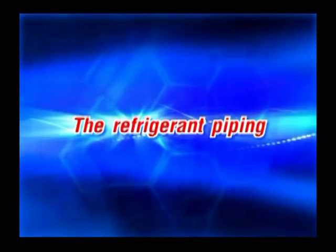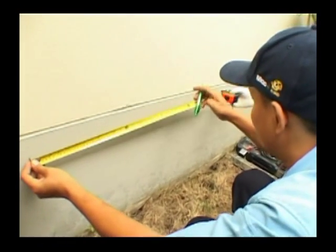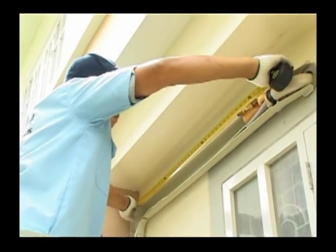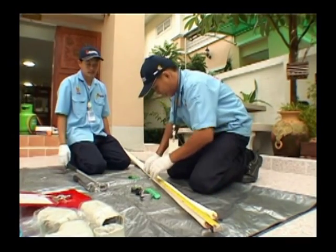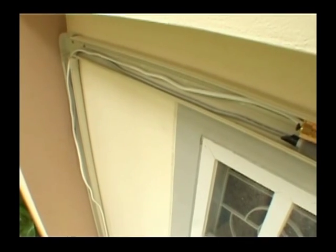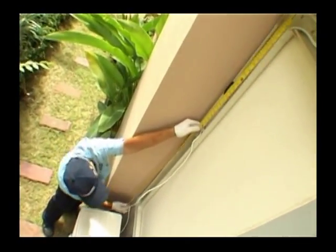The refrigerant piping. It begins with finding the position of the outdoor unit. Then measure the length of the pipes from the flared joint of the indoor unit to the flared joint of the outdoor unit. The length of the PVC pipe must match the distance between the tip of the drain hose of the indoor unit and the area where water is discharged.